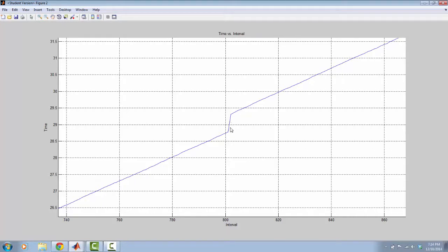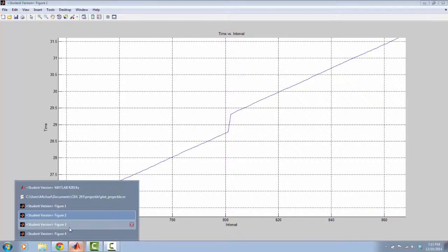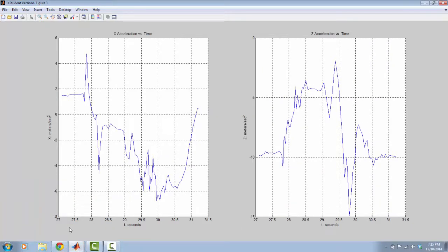And this half a second delay is something that I programmed into the microcontroller to allow the motor to open the hatch and deploy our water balloon, making sure it has plenty of time before closing. Just under 29 seconds is where this occurred. Adding about 2 seconds around that should give us the time for our data. And I took the accelerometer data just for this time, so I have going from about 27 seconds to 31 seconds. And I went ahead and actually graphed this data.